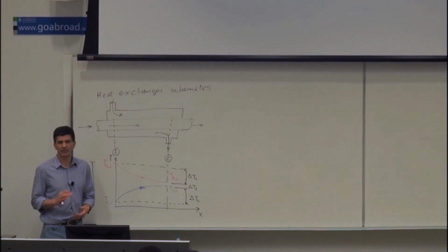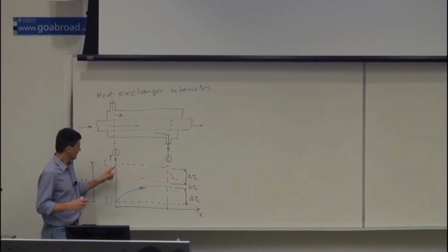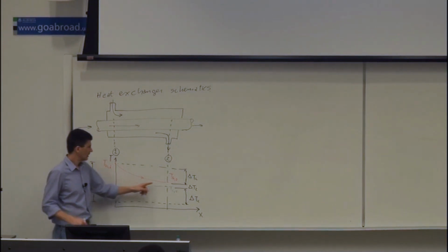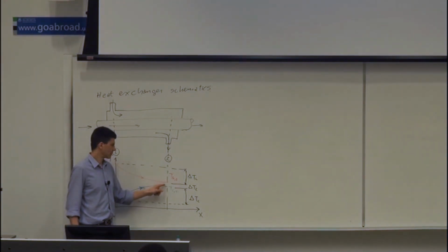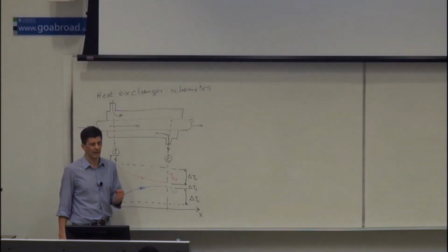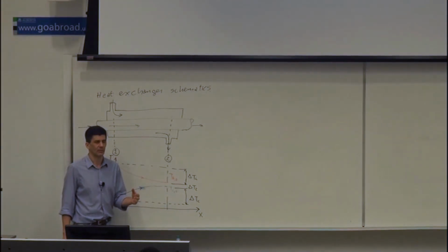Intense because it's a big difference in temperature, right? Because we have a big difference in temperature, the temperature change is relatively fast. So the slope is steep. Now here, the temperatures are quite close, right? So we have a shallow heat, a weak heat exchange, and shallow curves.